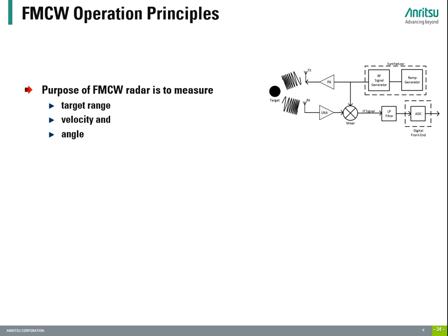Let's consider the simplified block diagram here on the top right of such a radar system. A ramp generator is modulating an RF generator, whose signal is transmitted via an antenna. The same but reflected signal is now received and downconverted to an intermediate frequency by the same signal as transmitted, low-pass filtered and sampled by an ADC, as we can see here.